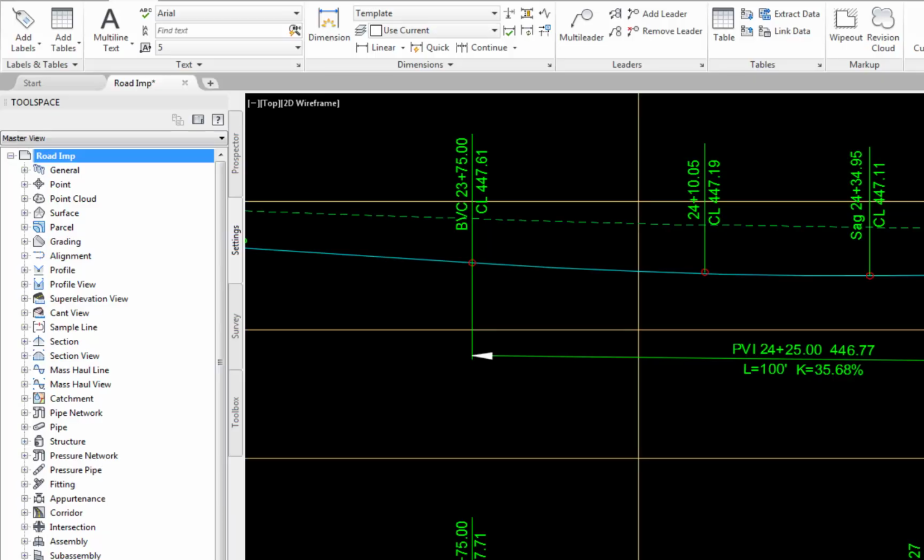When a label is inserted into a drawing, the appearance and all aspects, text size, layer, orientation, leader, etc., of the label are controlled by the settings of the various parameters contained in the Label Style Composer for the particular label style selected. One or several parameters of a label may be modified in the Label Style Composer prior to or after the label is created.